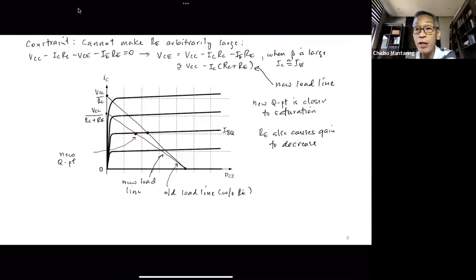And it is the collector current across the collector resistor that establishes the output. So if my collector current changes bigger, then the change in my output will also be bigger and I will have a bigger gain. So that's why this has a larger gain than this. No? Now you're going to study more about that when we take up the details of the transistor amplifier.